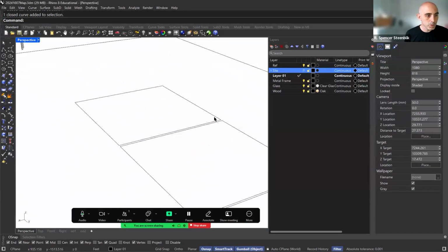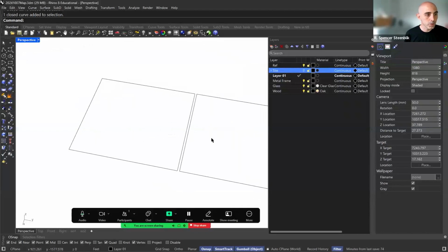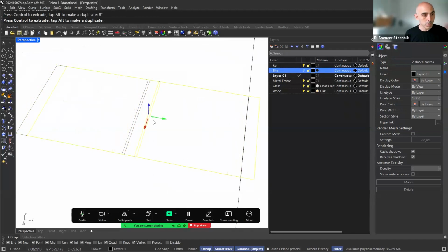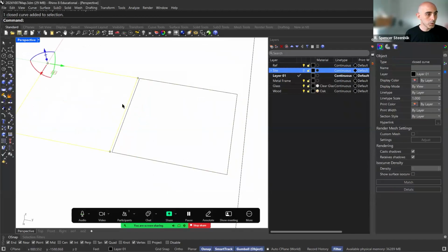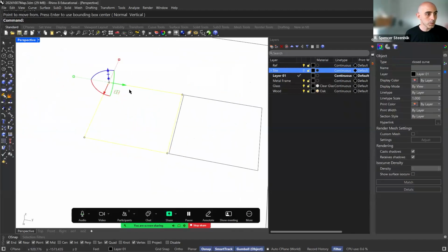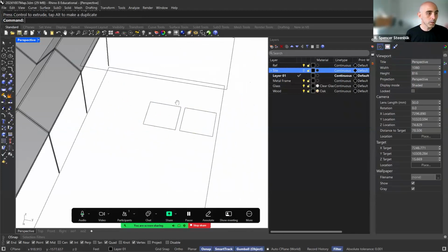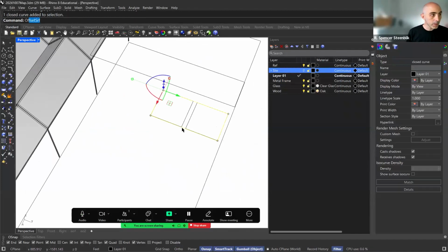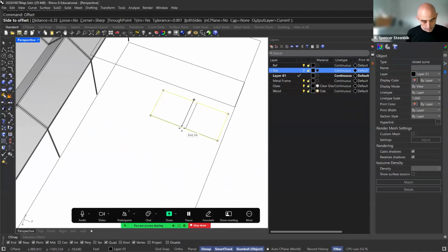And this wants to have some wall thickness to it, right? So you've got to think about that wall thickness. So we're going to offset it by 8 inches just to be clean. And we'll do the same here inside, another 8 inches. 8-inch walls are pretty thick, maybe a little bit overkill, but it'll do the trick. Now we can take this envelope and offset that by 8 inches.